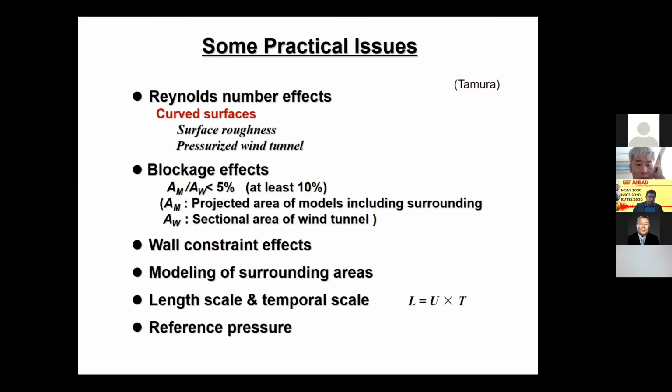Here are some practical issues. The Reynolds number is a very difficult problem, especially for curved surfaces. If you study a dome, because the separation point will shift, it's not stationary. So it will have a stronger Reynolds number effect.